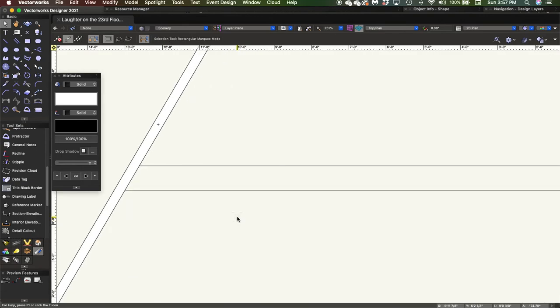and I'm going to activate the circle tool. Its shortcut is the number 6, but I'm going to click on that. And again, in the toolbar, I have a number of different options. For this one, I'm going to click the radius mode. So you're dictating the size of the circle based on its radius. I'm going to click once to start my circle, and then you'll see as I come out, I can make that circle larger or smaller, and it'll tell me what that length is.